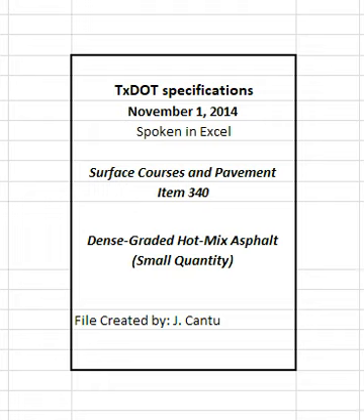4.3.1.1 Target laboratory molded density when the TGC is used. Design the mixture at a 96.5% target laboratory molded density. Increase the target laboratory molded density to 97% or 97.5% at the contractor's discretion or when shown on the plans or specification.